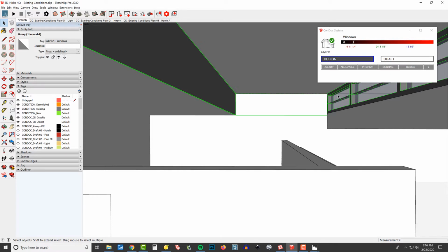It's like this, it's a window 2D graphic. The other way you could do it, I don't want to jump through the hoops of creating anything custom just to show these ceilings on this plan. So I think just doing that quick cheat is justified too, because those windows are in a unique place, so this 2D graphic I'm showing is more about the unique ceiling conditions happening than it is about the windows.